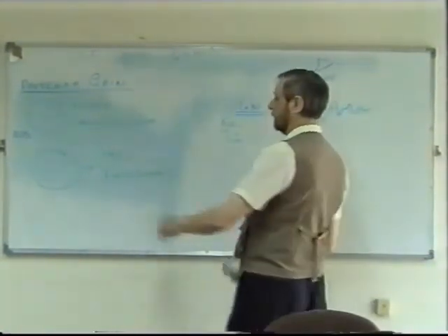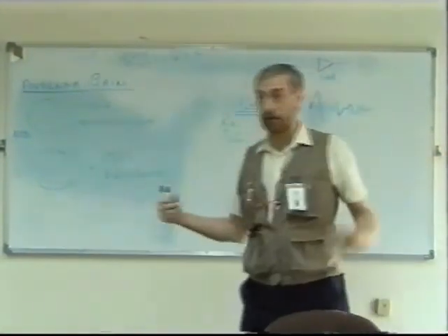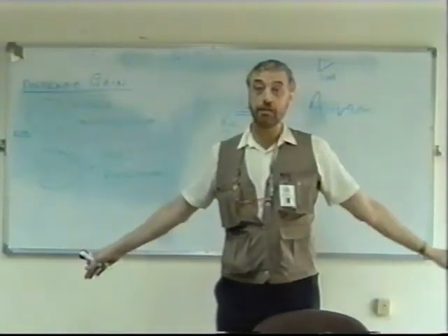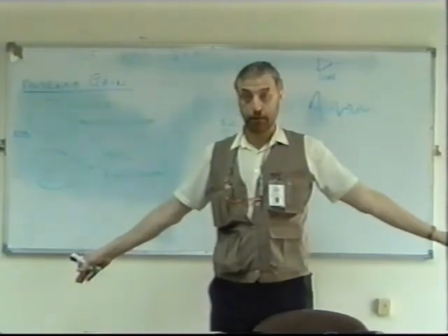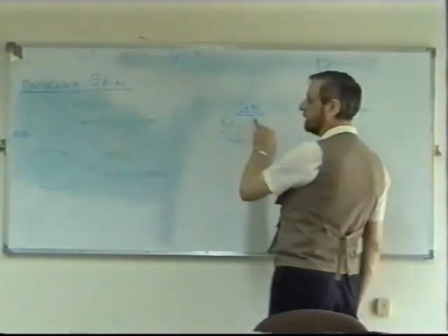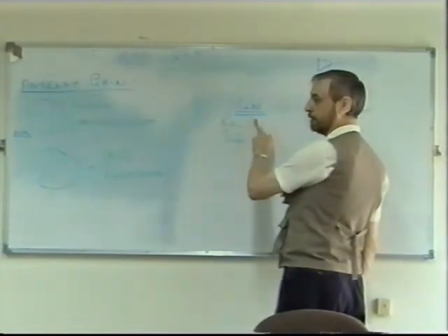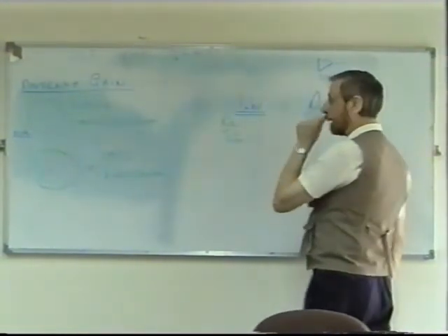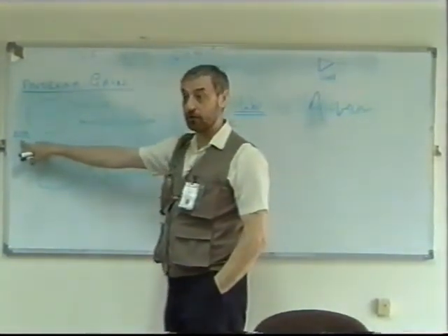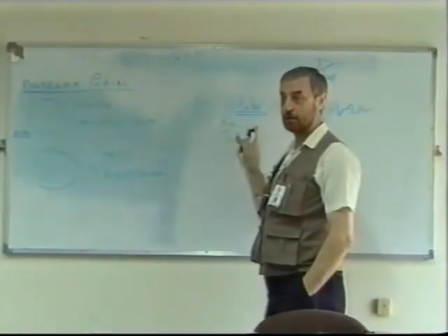So I have a 100-watt transmitter, but by the time the signal has reached the receiver, because it's spread, don't forget, in all directions in this example. Yes. We're spreading it behind, above, below. Most of it, as you can imagine, is wasted, isn't it? Particularly on a point-to-point. So by the time it gets to the receiver, we might only have 1 microwatt of power to induce a signal into the receiver. Now let's say that's okay, but if I reduce the power of my transmitter to say 10 watts, then we expect this to go down, don't we? Yes. And eventually it could go below the level of the noise.